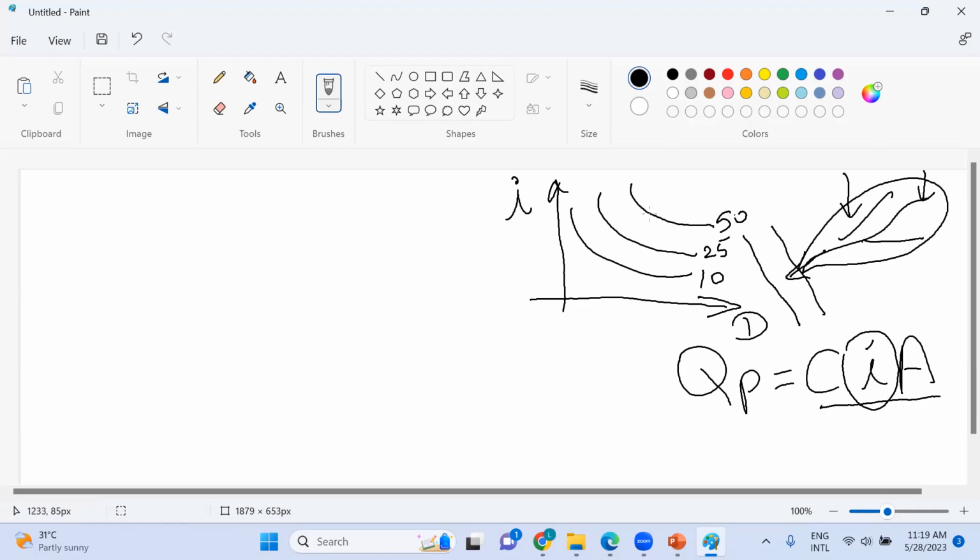Now, depending on the return period that you use, this rainfall intensity is going to be different. The higher the return period, the higher the rainfall intensity, right? So why is this even important, or how does it relate with the risk, the hydraulic risk?